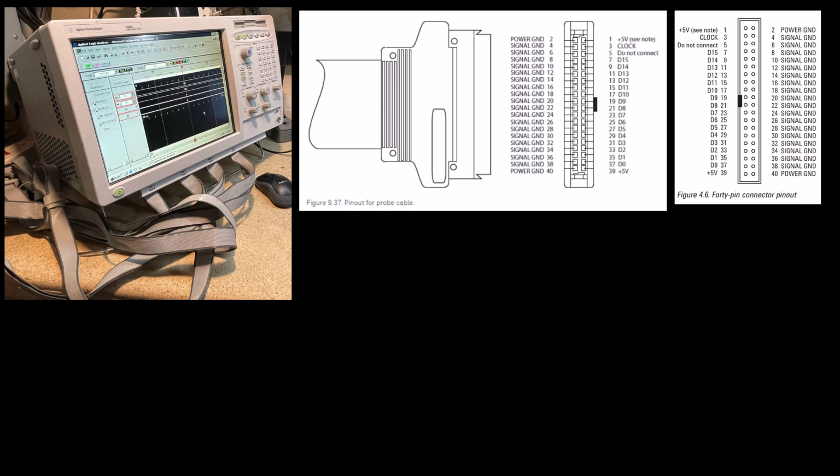Now my goal would be to basically get that to plug right into whatever system I'm trying to debug. And something like this would be a nice header to have just to plug that cable directly into. And that way I can connect up, grab all of the 16 data lines, and there's also a clock line, so there's really 17 inputs per connector. So 17 times 8 is where you get your 136 inputs that this device can handle.